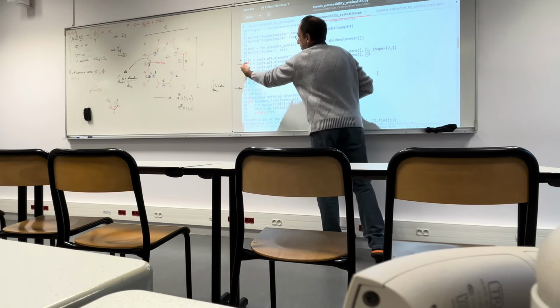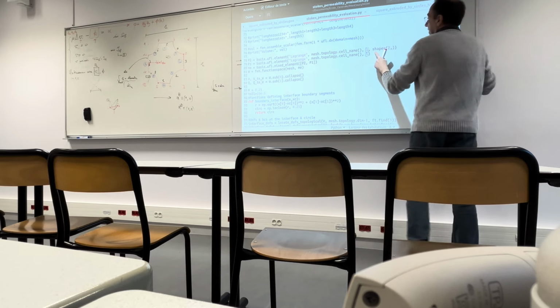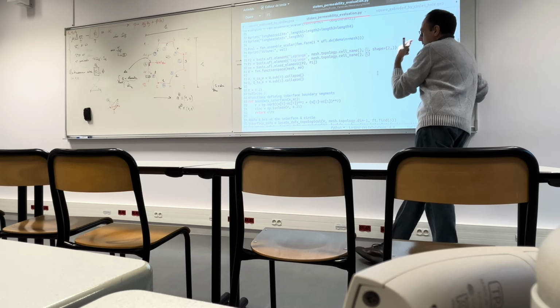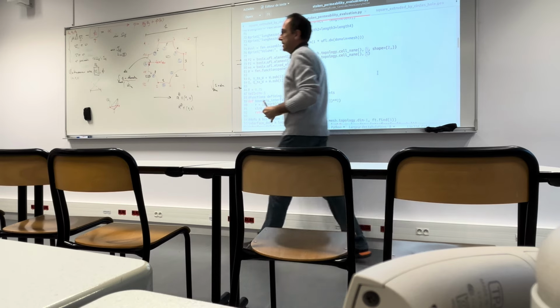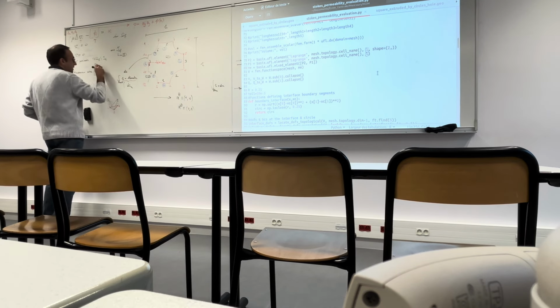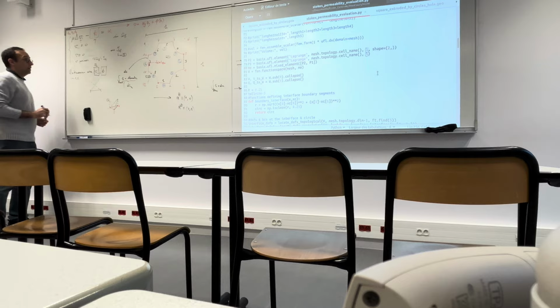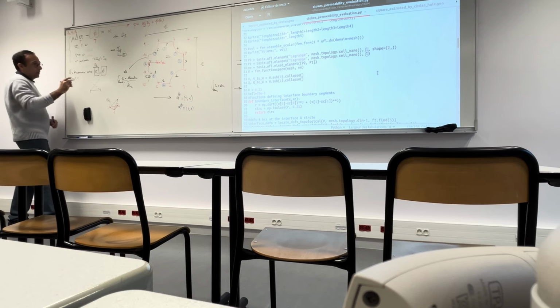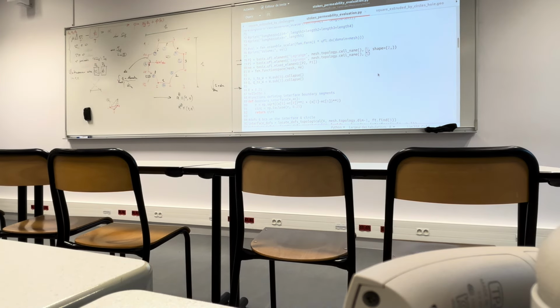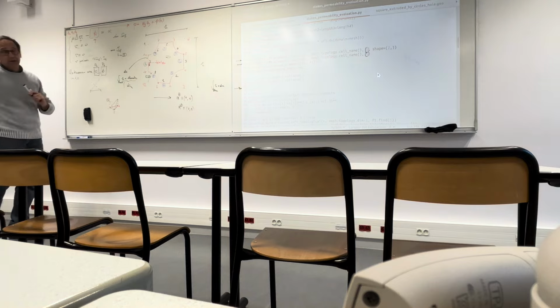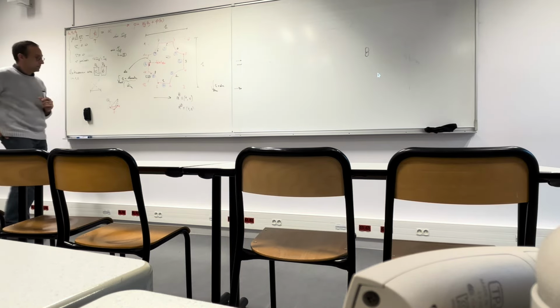So P2 are Lagrangian elements of vectorial kind, and this shape equal to means that the dimension we are looking at is 2 because we are in 2D and we are considering a vector field. And here we don't specify anything, which means that it is a scalar. So P2 is the space where we define Lagrange finite elements for velocity, and P1 for pressure. For phi, the periodic part of the pressure. Okay.